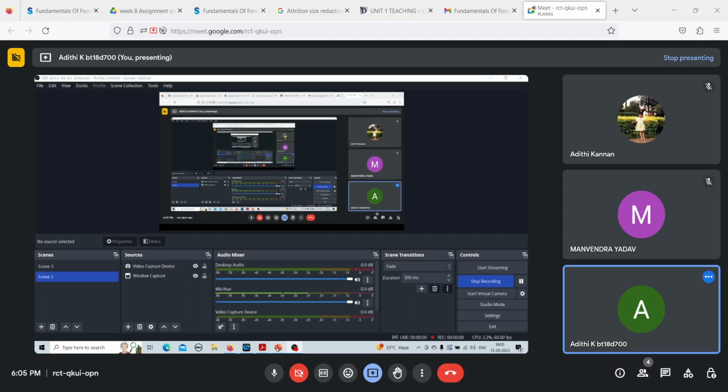So dE by dx is directly proportional to the size of the particle, by a power law model. So dE by dx is equal to minus c x bar minus m. Here you have a minus because there is a size reduction happening. With increasing energy, you are reducing the size, which is why you have a minus sign here.